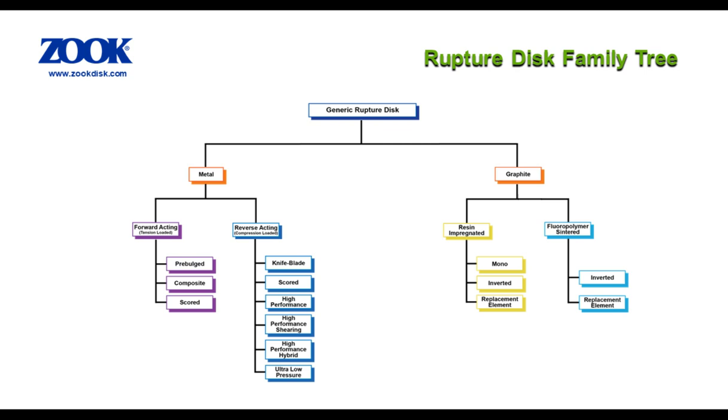Resin impregnation is the first and most common process used. Various resins have been used over the years, but typically they are phenolic-based. Through a process that includes pressure, vacuum, and temperature curing cycles, the graphite pores are filled with cured resin that renders the graphite material impervious and suitable for use as a graphite rupture disc. Resin-impregnated graphite provides good corrosion resistance, inert material with non-ion contamination, temperature stability, and predictable results.